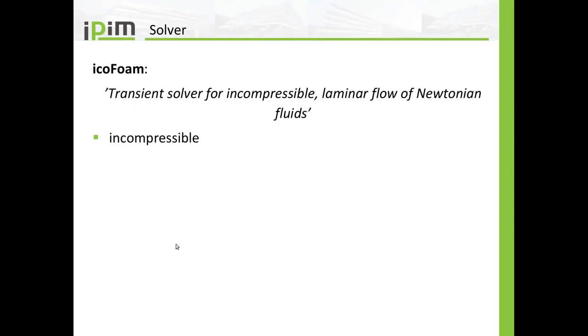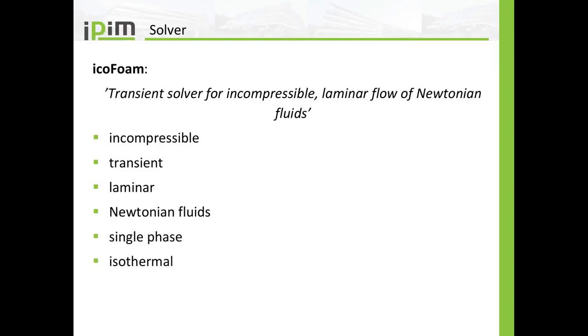For that we will use the icoFoam solver in OpenFOAM. The official description is that it is a transient solver for incompressible laminar flow of Newtonian fluids. So this means that this solver is incompressible, it is a transient solver, it only works for laminar flows and only for Newtonian fluids, it is a single phase solver, and it is an isothermal solver.